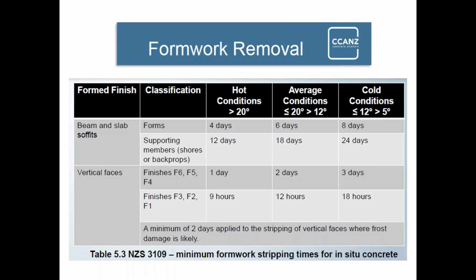If you look at CANZ, which is Concrete Association New Zealand, they've got some guidelines on what sort of finish you want and when to pull the formwork off. The earlier you pull it off also affects the actual finish you get. If you look at this, for the lower grade finishes, you could pull that formwork off in 12 hours. But if you wanted higher grade finishes, then you'd want at least 2 days, if not 3. So remember, the longer you can leave it on, the better it's going to cure.